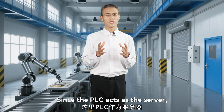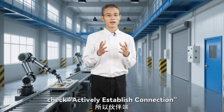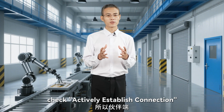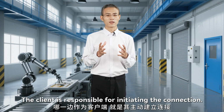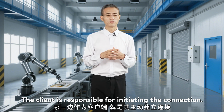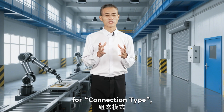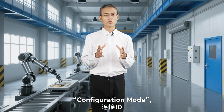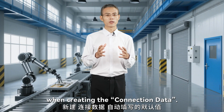Since the PLC acts as a server, check actively establish connection on the partner side. The client is responsible for initiating the connection. Accept the default values for connection type, configuration mode, and the connection ID when creating the connection data.